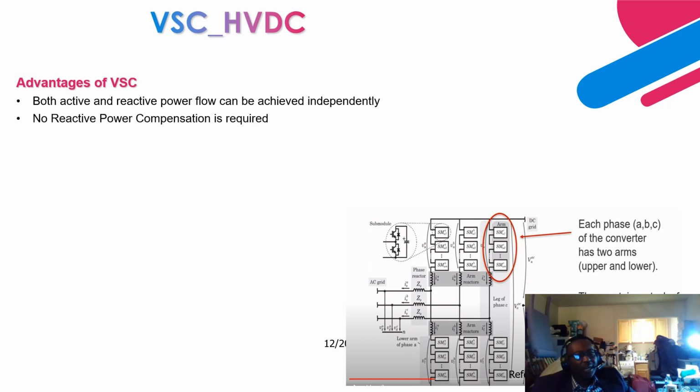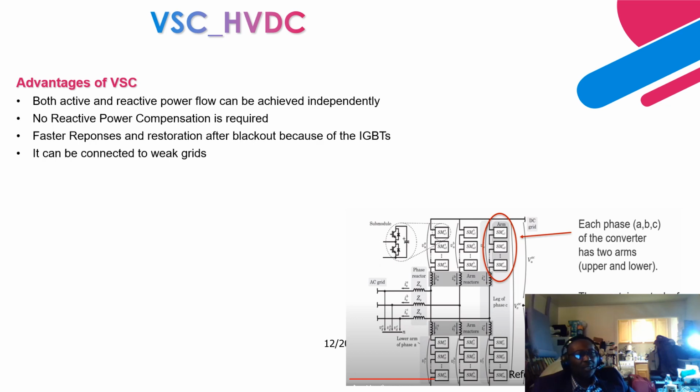And also it doesn't require reactive power compensation because it can synthesize its own voltage. It has a much faster response, due to the use of IGBT, so it allows faster restoration when you have a blackout.